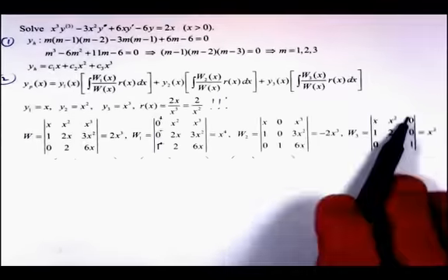Okay, now this is where we end up making some assumptions. Assuming that the bending is small, so that the deflection and its derivative aren't too big, what that's saying back here is that this distance down here isn't too big, whatever too big means, and also the derivative. Even if the deflection isn't too big, it could come down a little bit with a very steep slope in some situation.